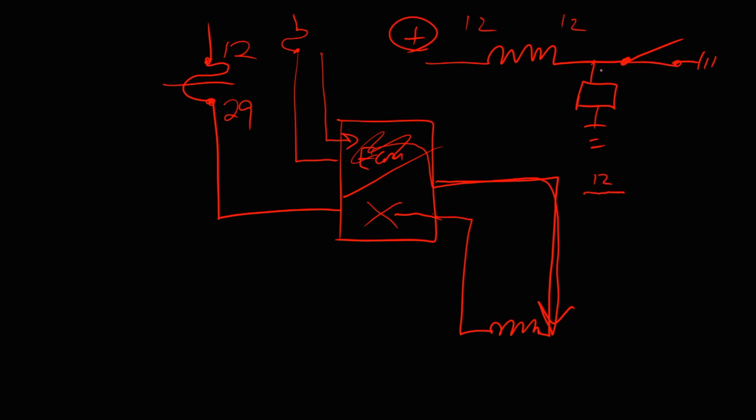What happens when this switch closes? Voltage goes to ground. So you'll see this, right? Looking at a scope waveform, how long this switch stays closed would be how long our pulse width is. Fuel injector maybe, right? Now open the switch back up. This comes back to 12, but it doesn't. It comes up to, typically on a fuel injector, you might see 100 volts. You might see a 100 volt spike. Why did that do that? Well, when we had current flow, which is in this low portion, what was this coil doing?